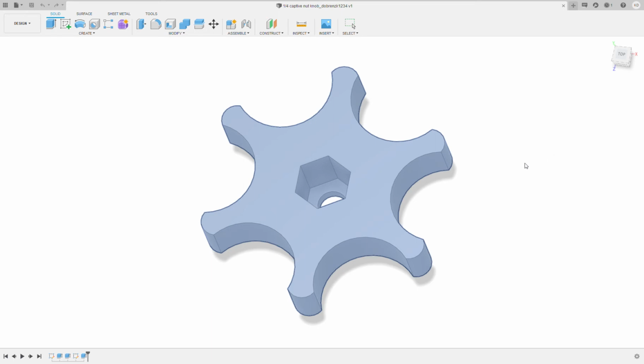Now, under sheet size here, you can see that I have several options. I have two A's, a B, C, D, E, and if you look, it gives the inch dimension of each of these sheets. And an E is a very large sheet, 44 inches by 34. I could show a lot of very detailed information on a sheet that size. And sometimes, if it's a very detailed, large assembly, it would need a large sheet to communicate information.